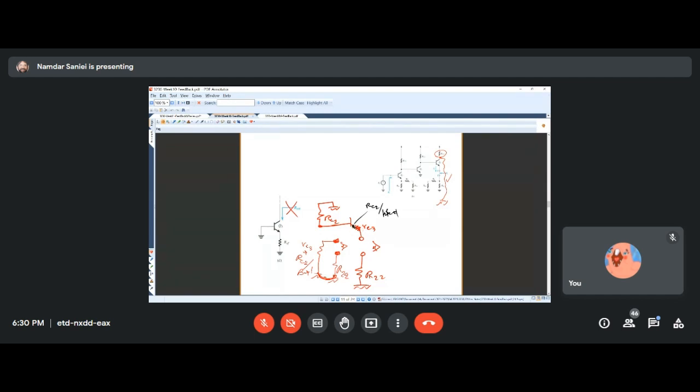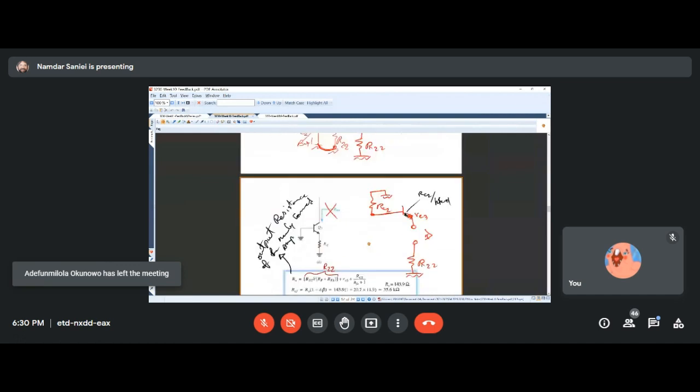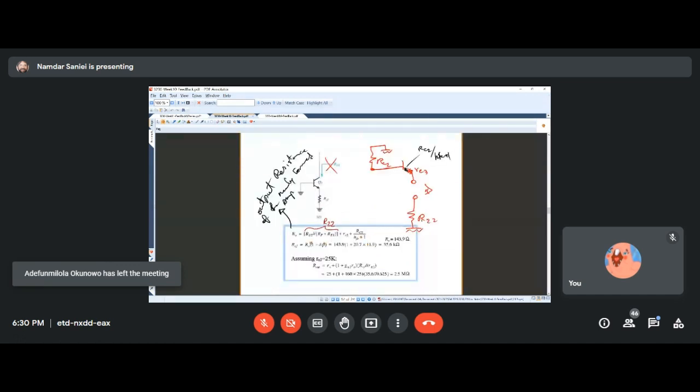Going to ground, it's in series with this R22 when we are looking into these two. But soon we realized that if we follow that, there will be an output resistance that we have to multiply by 1 plus A beta, by the way, and then that fits in the loop as the output resistance under feedback of the loop, which is underneath the emitter terminal of the transistor.